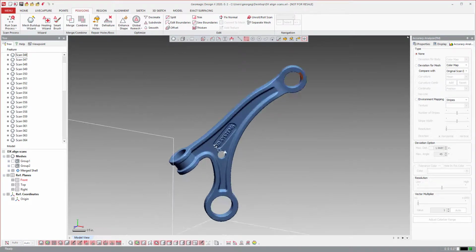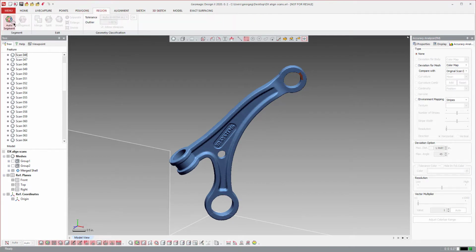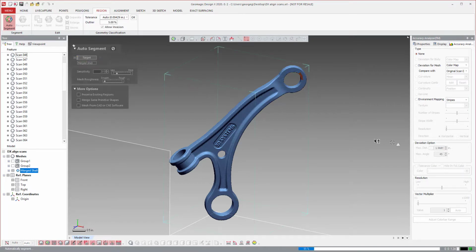So in order to do that, you don't have to create regions, but I'm going to go ahead and create regions because it also shows how to do that as well. So if I come in here and I like starting with 20 and select the mesh that I'm working with and then hit apply. While that's running, I'll just explain what the region group is. This is a triangle or polygon object, right? And those triangles are flat, three-sided objects, right? Now, the triangles have neighbors, and if they are perfectly flat, there's a 0-degree angle between those neighbors, right?